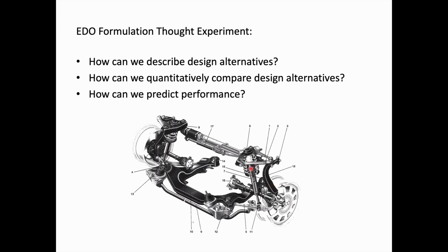And here we have an upper control arm, lower control arm, steering knuckle, or the uprights. And here it's a front wheel drive car. It might also have rear wheel drive, I don't know, but here are the half shafts, the drive shafts that come from the transaxle here in the front of the car. And we also have the steering system up here, the steering rack, and this is what exerts a force to the steering knuckles that then turn the wheels.